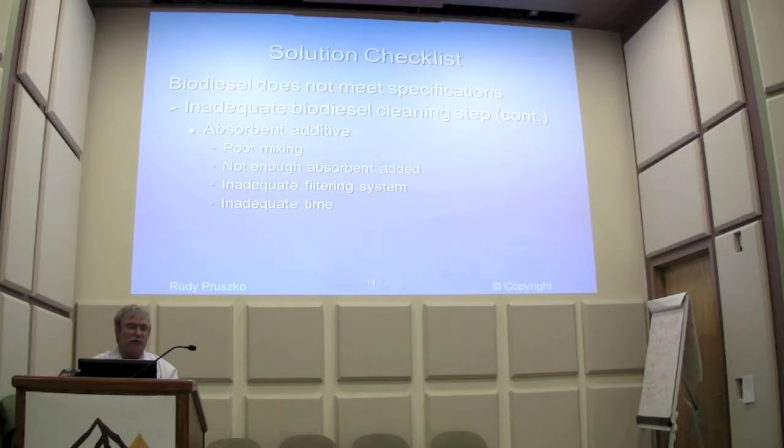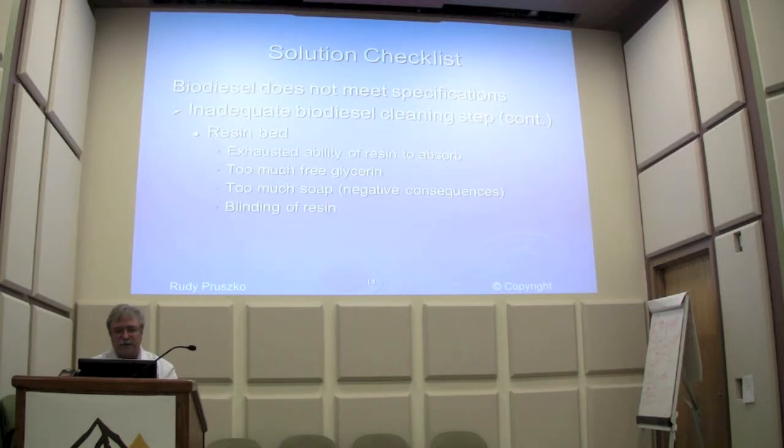And if you don't have a good filtering system, some of the absorbent will end up in your biodiesel, show up in the ash spec when they do the final analysis. So you want to have enough time to make sure that you can have that physical contact with the impurity.